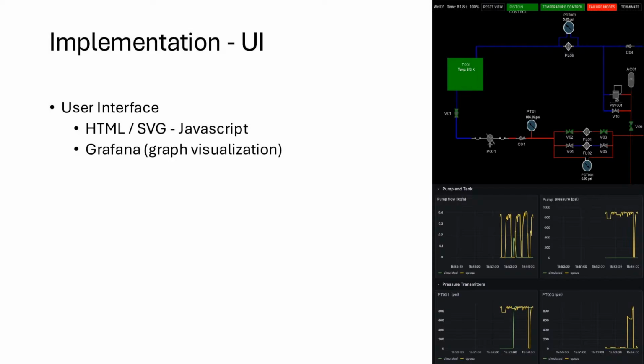After I describe the architecture and the integration, this is what the end user will see, the user interface. The digital twin runs simultaneously with the actual hydraulic equipment. It receives live data like pressures, valve positions, pump speed, and continuously calculates what the system should be doing according to physics and control logic. In other words, it acts as a real-time sentry of the physical system. When they begin to diverge, even slightly, the digital sentry detects the deviation immediately. In parallel, we have live dashboards providing analytical insights, trends, and statistical deviations.